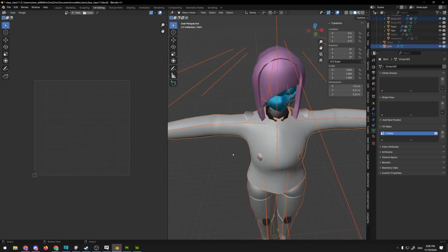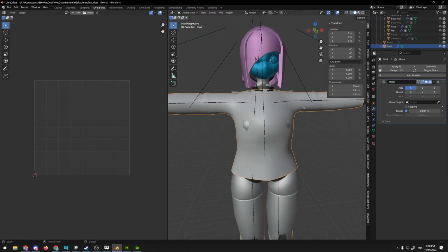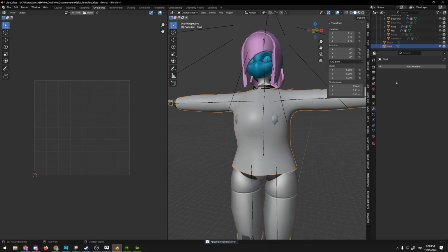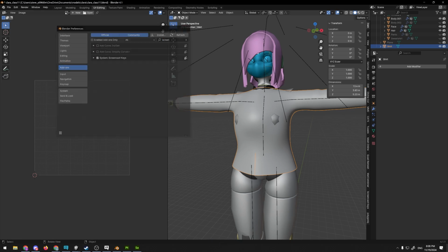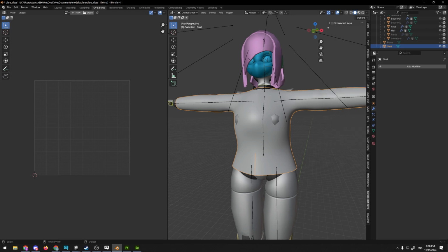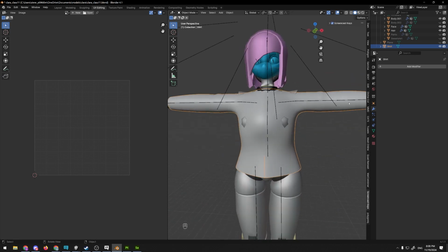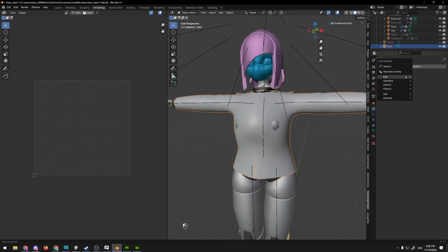If I take our object, and not that we need to subdivide, although we always can, it's an option. Apply our mirror, add modifier subdivision surface, 1, apply. I'm using Control A for that. I don't think you're seeing my keyboard shortcuts. Screencast is not activated. Fascinating. Oh, there you go. Keyboard shortcuts. Cool. I used Shift A to apply, I think.